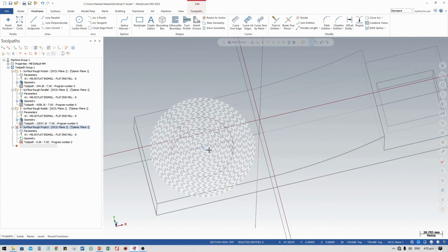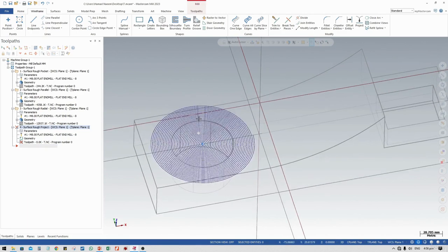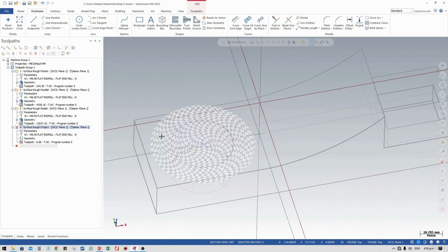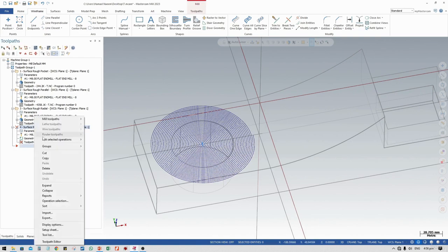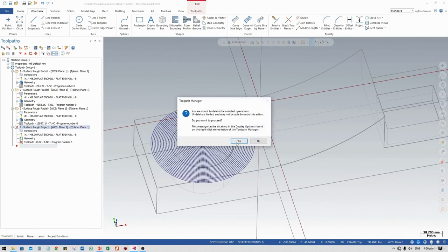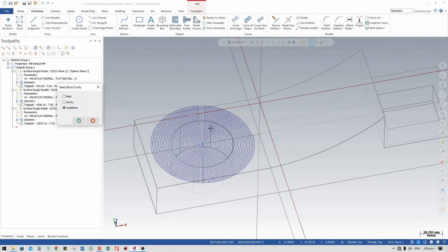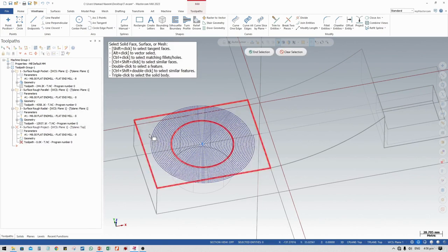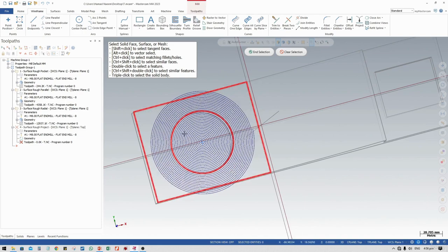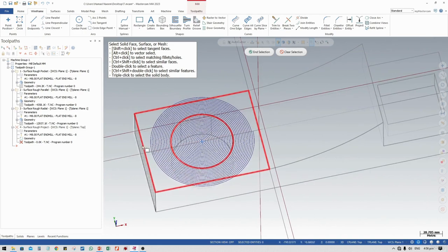The toolpath will work according to your desired wireframe. Here what you see is 2D geometry, and I have projected this tool on this surface. Let me show you. Let me delete this first, and again go to milling toolpaths and project. I just want to machine that area using those curves. So this should be my surface area.